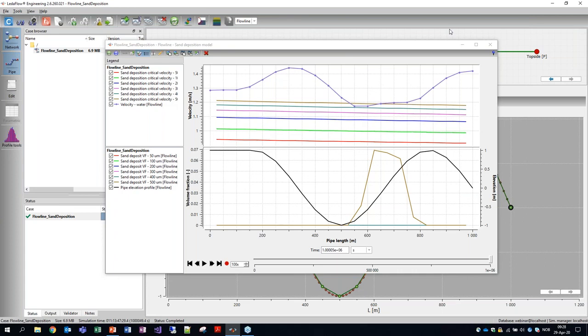Is that an instantaneous thing, or does it take time to go back? Yeah, as you can see in this simulation, just depositing the sand takes time, and the re-entrainment also takes time, because we have this kinetic mass transfer term for the sand. So it's not instantaneous, but it's relatively fast compared to the time it takes to transport the sand through the pipeline. Very good.